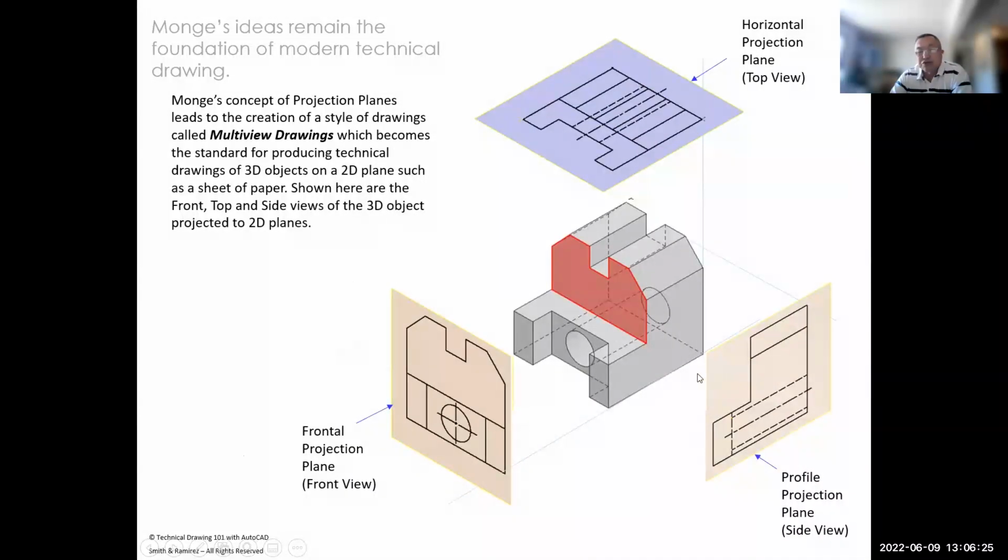And this is the three views of the projection. Remember, when we do the projection, the projection lines are all parallel. Imagine, although we don't have those lines marked here, every point has a projection line going from the object onto the projection plane. This is called the projection plane, where the drawings are produced. So all those lines are parallel. Remember, that's a very unique property of projection.